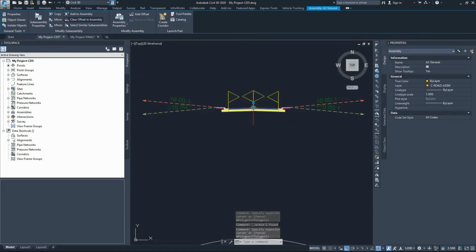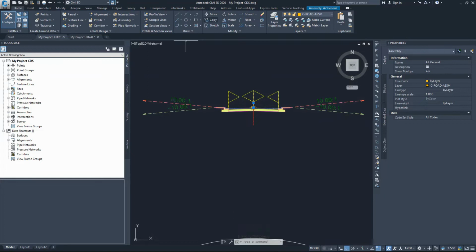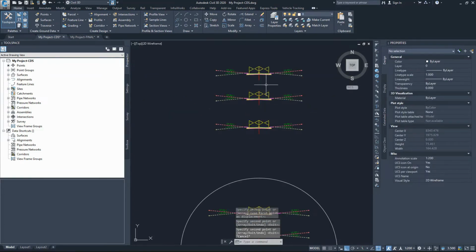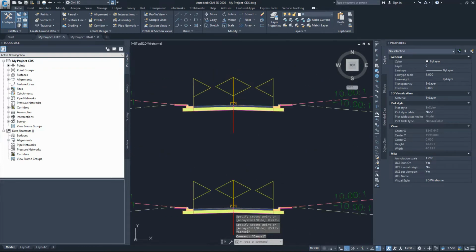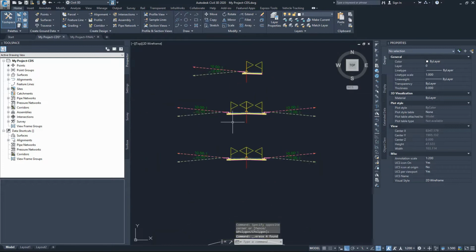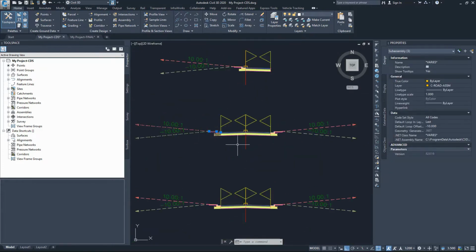We don't know yet which one we'll need. Let's create them both. So I'll copy this once and twice. For the first one, I'll create left hand side. So I'll delete the left hand lane and the right hand curb and daylight and sidewalk. Now I'll create the opposite, those and that.